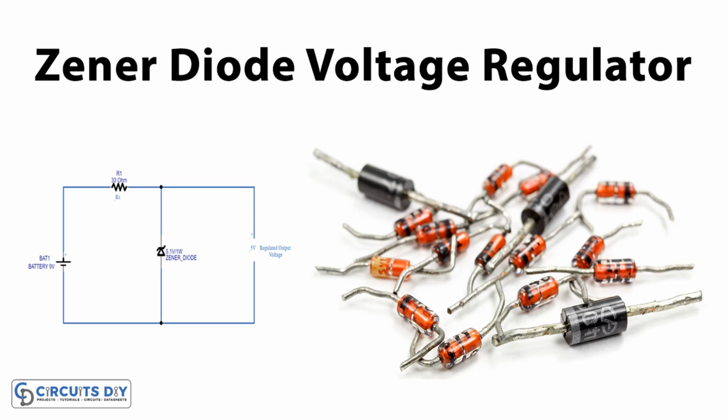6. Current voltage, IV. Characteristics. Forward characteristics. In the forward direction, Zener diodes behave like regular diodes with a forward voltage drop of about 0.7 V for silicon diodes. Reverse characteristics. In the reverse direction, the current remains very low until the Zener voltage is reached, at which point the current increases rapidly, maintaining a nearly constant voltage.